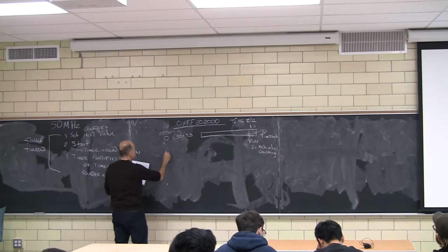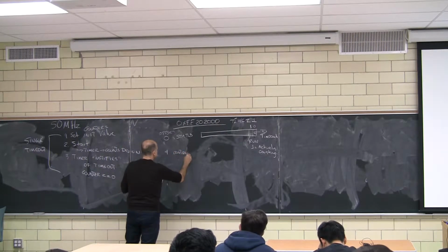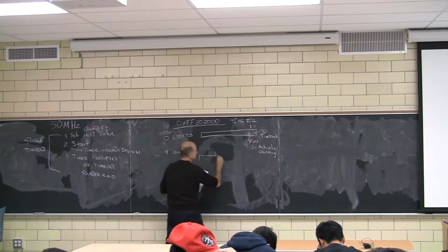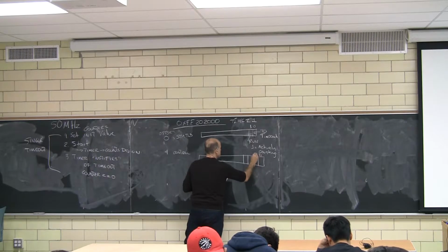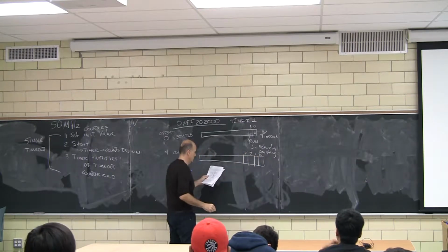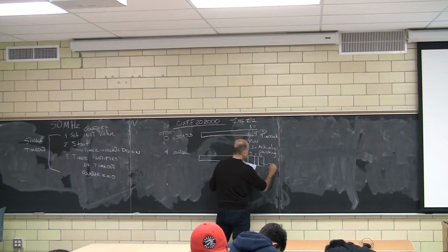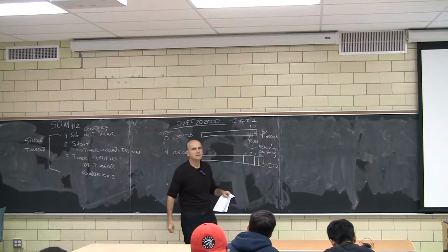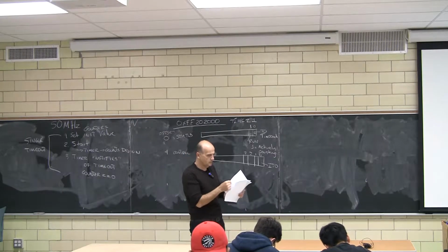This is the status register. Now at distance plus 4, we have the control register. And that guy is as follows. There are 4 bits that are relevant here: 0, 1, 2, and 3. Now, this is interrupt on timeout. If you set this to 1, the timer will raise the interrupt. And the interrupt is, I think, IRQ 3.